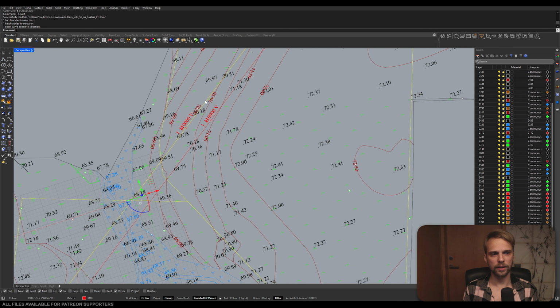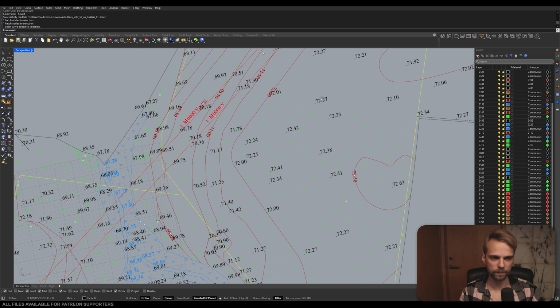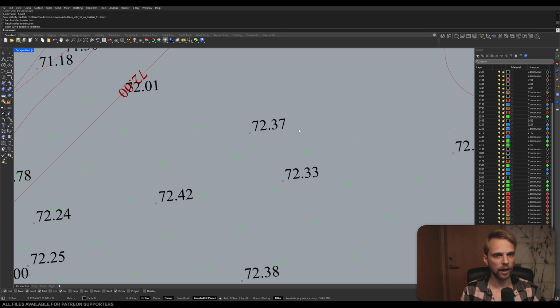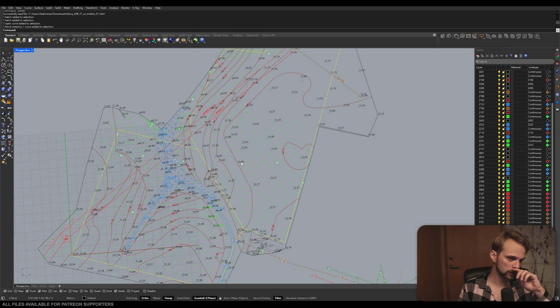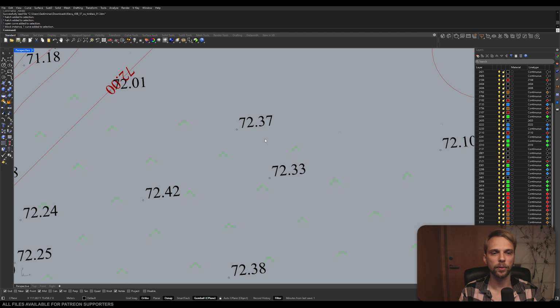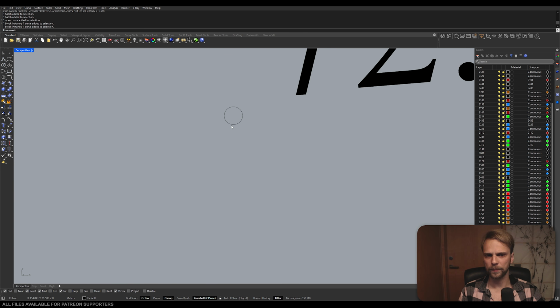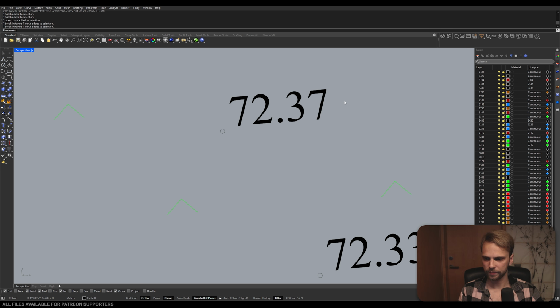These things are unimportant to us because for the three-dimensional construction of the site, the only thing we need are these marked-out height points, right? So the first step is to make sure that the height points are actually either a single point or a circular curve, and text.